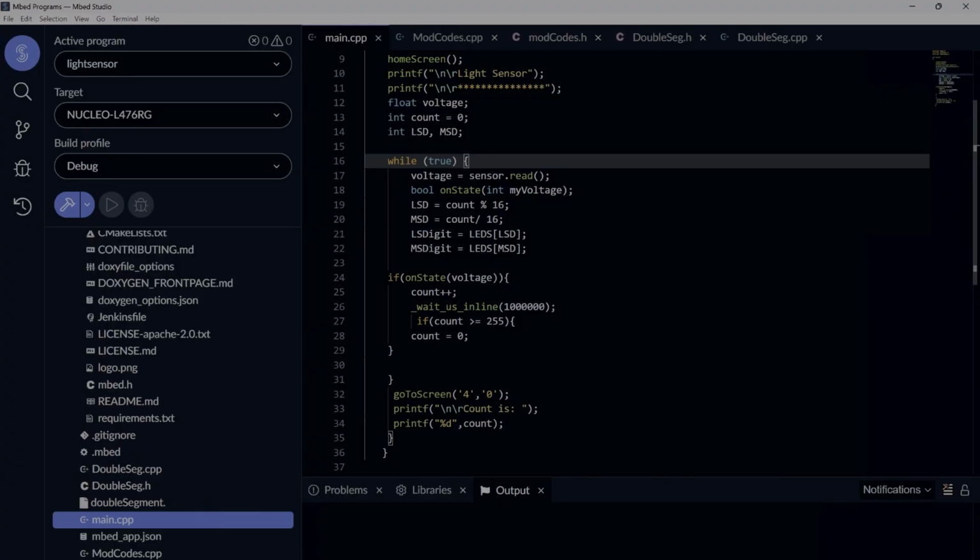It may miss this right here because remember when you put too many wait functions into your code, and there is ways around that, and we're hopefully one of these days, it's something called timers and tickers. Timers or tickers are a very clever way of timing it without freezing the microprocessor. So it's going to count. The thing will count forever.